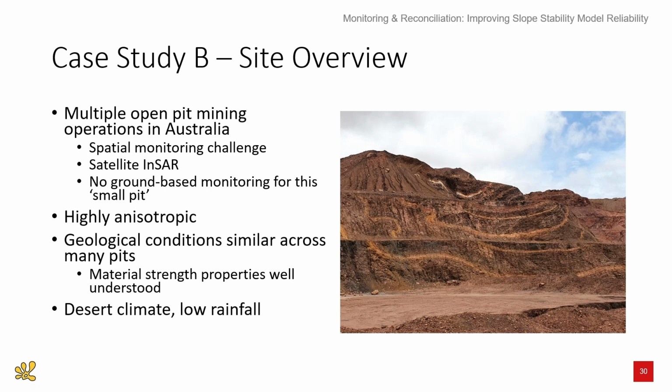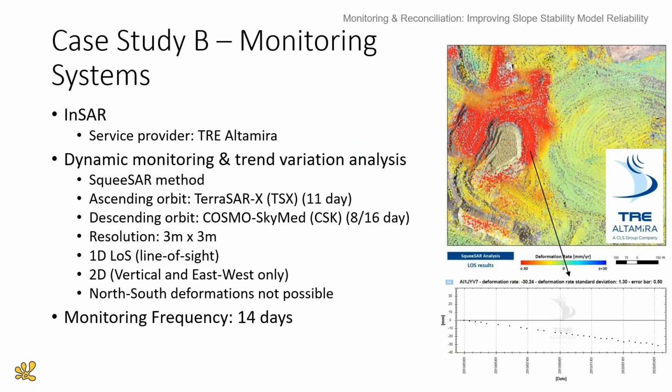The ground conditions are highly anisotropic, although the geological conditions are similar across many pits and material properties are understood quite well. So basically the monitoring system uses InSAR, in this case the provider's Tre Altamira, and a dynamic monitoring and trend variation analysis service is used. So time series data is collected every fortnight.